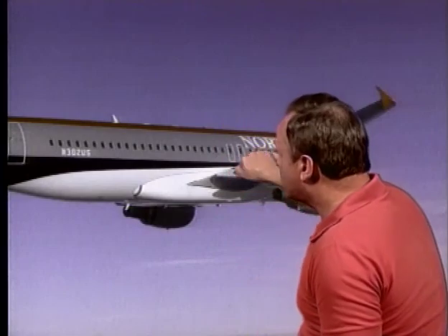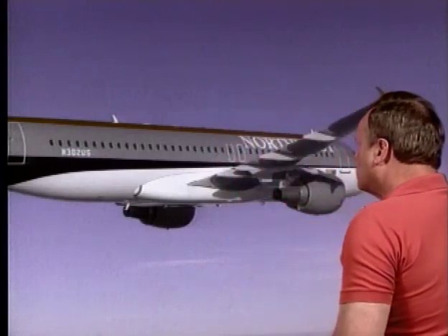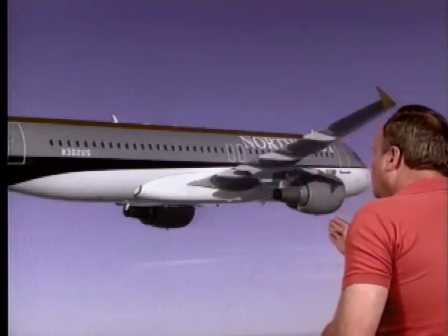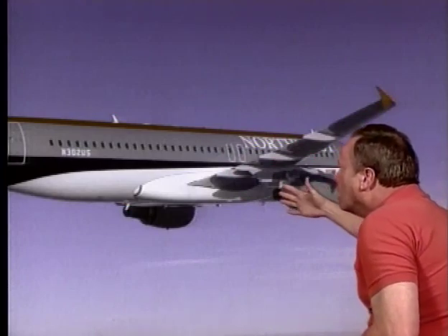Now, we're going to have to ask, first of all, what's the definition of constant power? And we think in this particular case, we're saying you don't change the power levers. You keep them the same. And then you turn on anti-ice. Well, what happens to an engine when you turn on anti-ice? You heat the inlet of the engine up, and you have warmer air going into that engine.